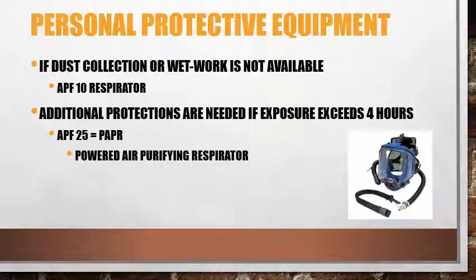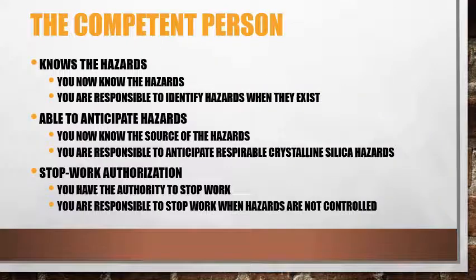Let's talk about PPE, or personal protective equipment. If dust collection or wet work is not available, an APF respirator is required. Additional protections are needed if exposure exceeds 4 hours. An APF 25 respirator, which is a PAPR, powered air purifying respirator, will be needed if you're using certain tools over 4 hours.